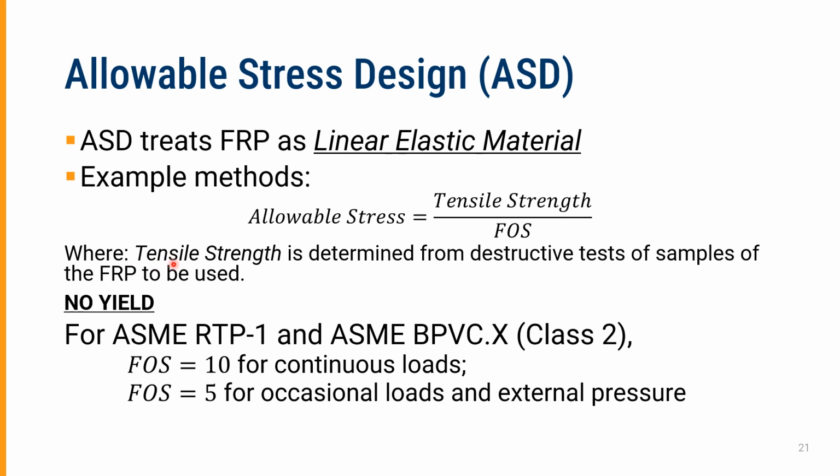Sometimes tensile strength is determined from destructive tests of the samples of the FRP to be used. In fact, in this case, tensile strength is determined that way. There is no yield for this equipment. It only fails in essentially a brittle failure.